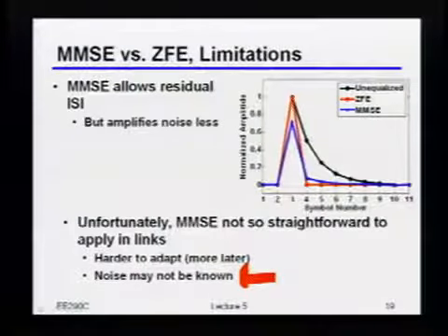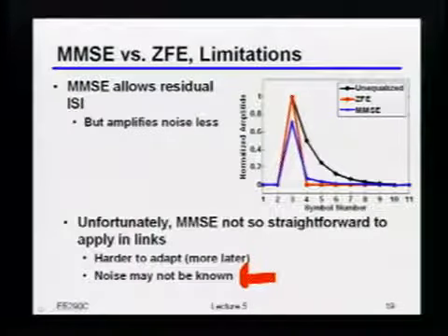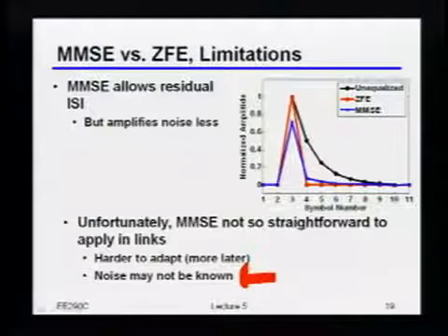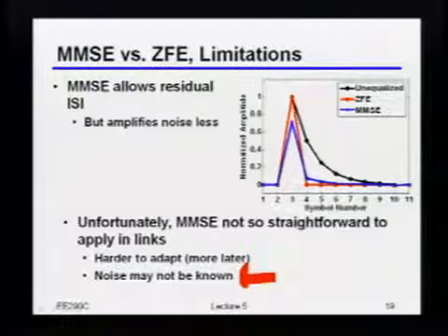Yeah. So if you do indeed estimate the BER, is it equivalent to doing an MMSE, or is it not exactly? Well, you could do what's called a minimum BER equalizer, and there are some people that have done some work on that. The biggest issue with most of them is that if you really want to do it the quote-unquote right way, and really minimize the BER, it takes a freaking long time to measure 10 to the minus 15 or 10 to the minus 20 for each and every single point. Sure, I'm just asking if you do indeed go down that path, and even if it takes long, will that actually be MMSE? Is it exactly the same? No, not exactly. It turns out that if you did something that was purely minimizing the BER, that would not necessarily be exactly the MMSE solution.